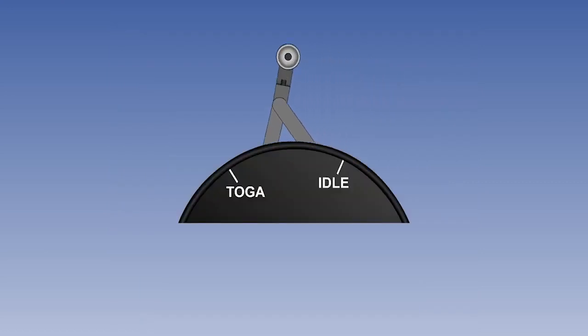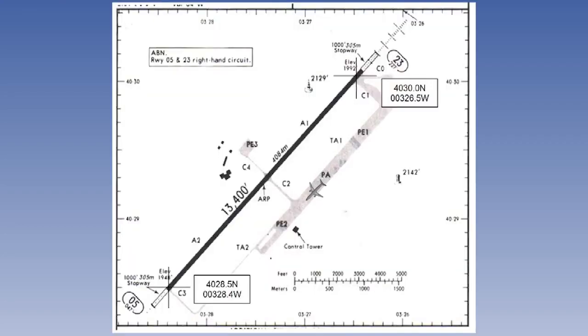As the takeoff roll is commenced, the throttles are advanced. A contact on the throttle quadrant is called the takeoff go-around switch, or TOGA switch for short. Operation of the switch automatically updates the FMC position to the takeoff threshold. It is also possible to input a displaced threshold. Suppose that we do not need to use the whole runway length and have decided to take off from 2,300 feet past the threshold. In this case, the pilot inputs a correction factor for the displacement distance, and the new position is automatically calculated by the computer as part of the update.